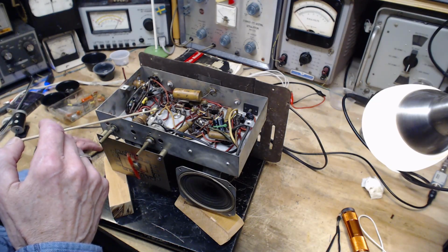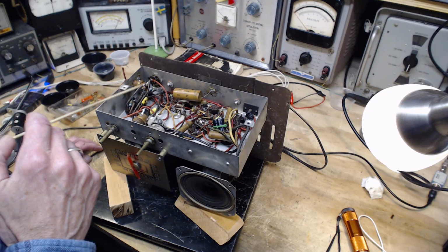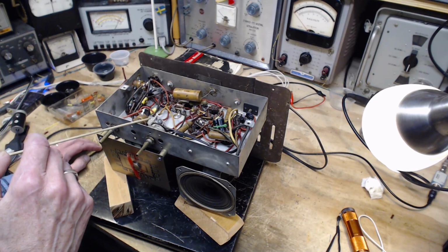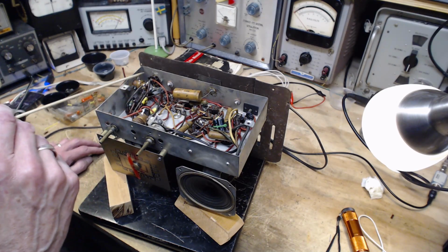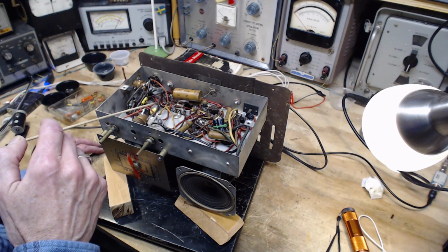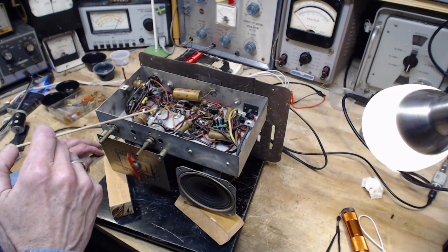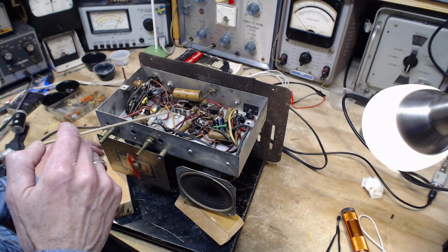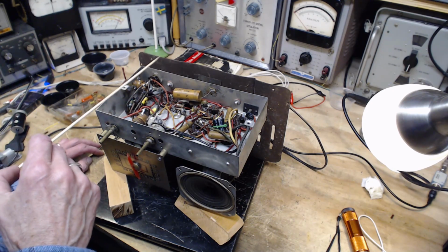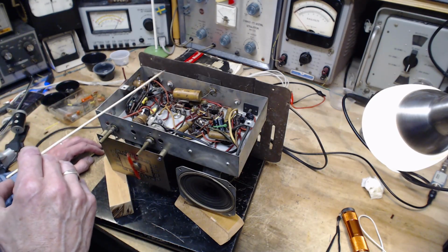There's nowhere for current to flow along this circuit, that's on the far side of this very large resistor. What that means is a very small change in charge can result in a large change in the voltage, or the pressure, of that circuit. It's very sensitive to charge coming into it because it's very high impedance. Almost an open wire, as I said.